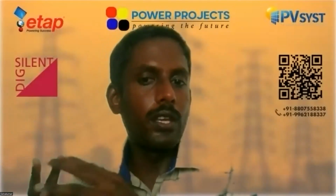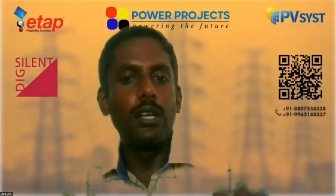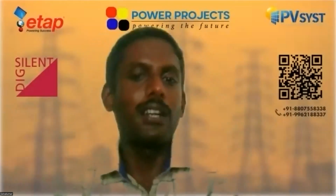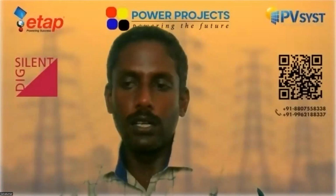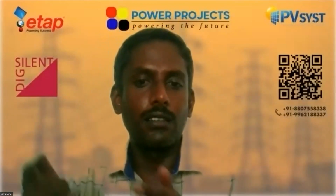So when you keep adding these intermittent resources like solar, the biggest challenge is not the increase in current, but that you have to deal with the minimum short circuit current. And I guess the NEOM project will definitely feel the same heat because it's purely renewables. There are no rotating machines. That means it's not a strong grid. Your fault current and your load current are almost the same. Then how do you detect the fault, right?